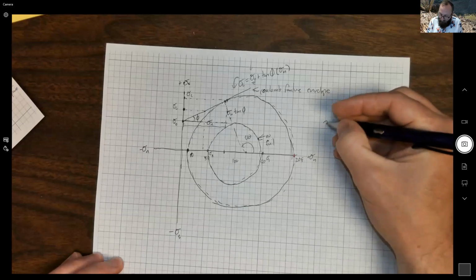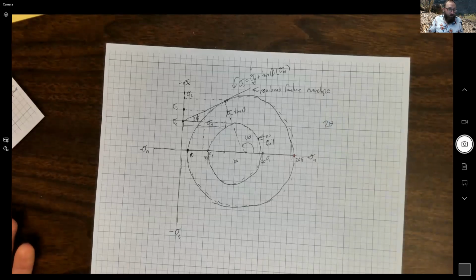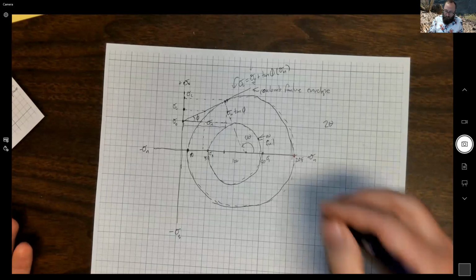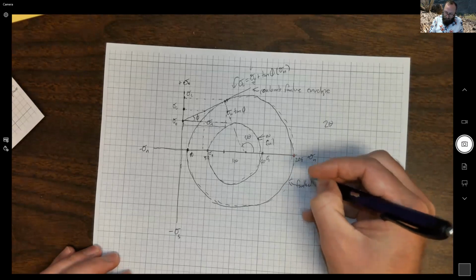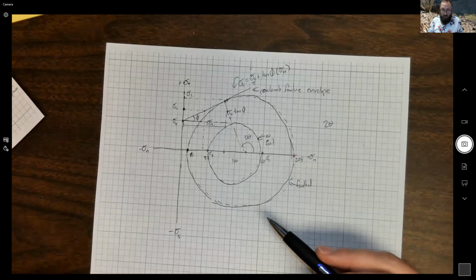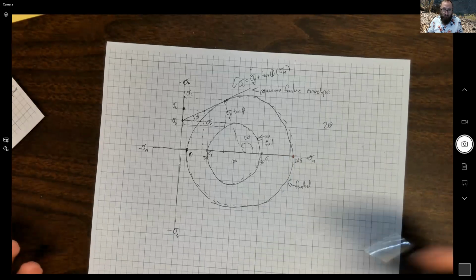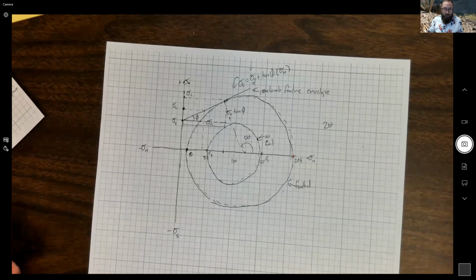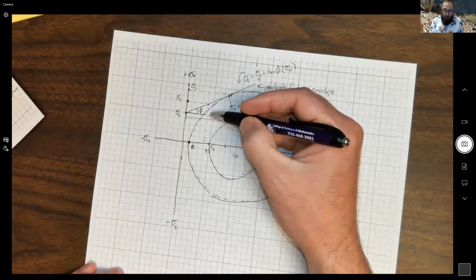So this failed, and the most important thing these experiments showed us, from looking at them from the perspective of Mohr circles, is we learned that the differential stress level at which a fault will form is greatly influenced by the internal angle of friction.